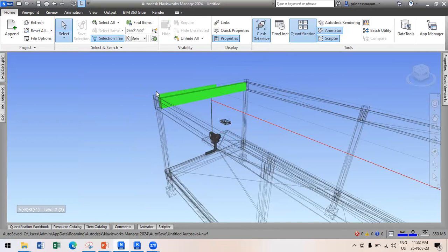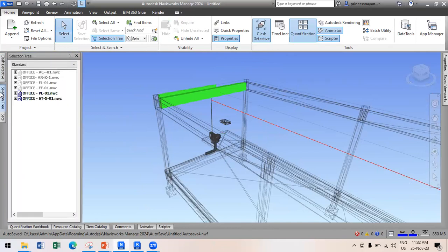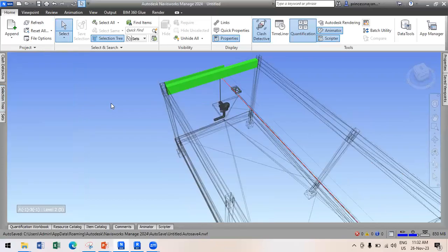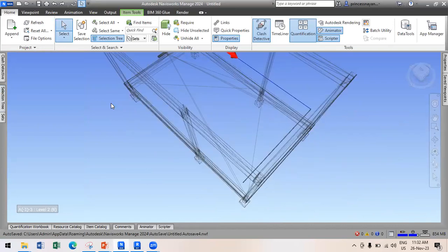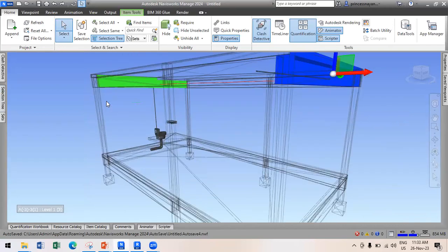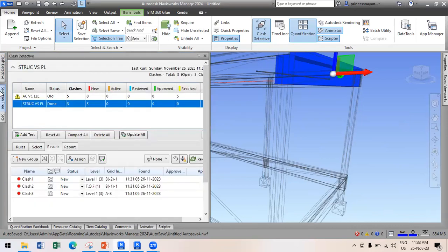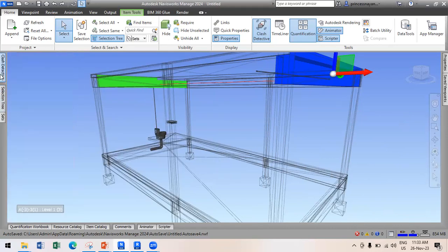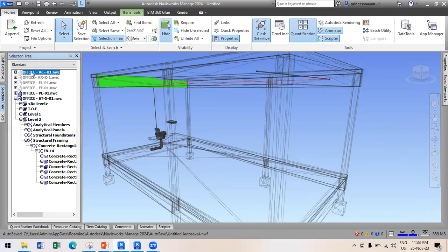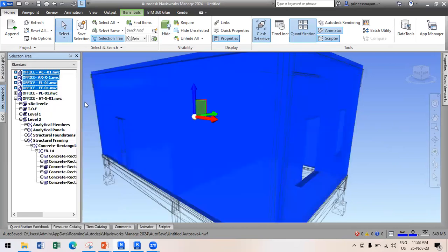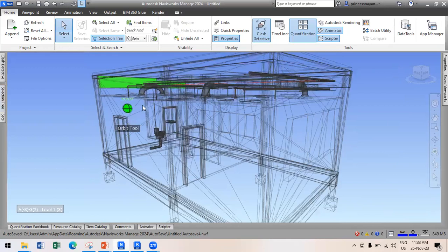Okay, finally, once we do, let us just do one last thing. We will do all clashes together and see how many clashes will come. Okay, let us do undo here. Now what I'm doing, see, I'm coming here to clash section. Okay, first of all, selection tree, and then here with height. So now this is for all the services.